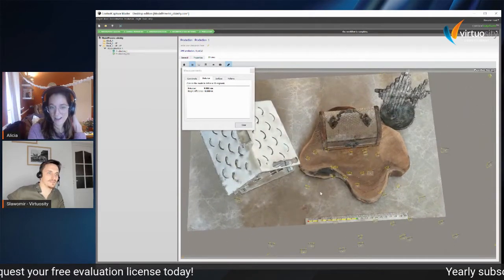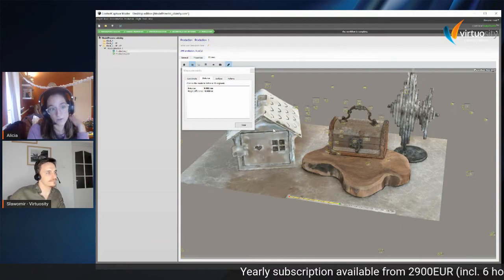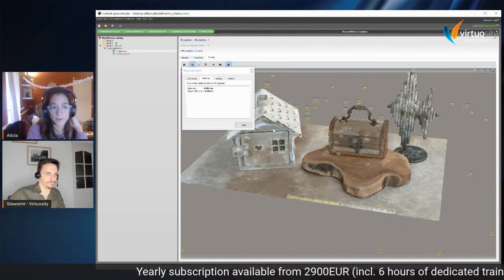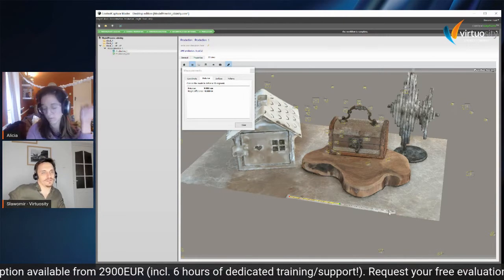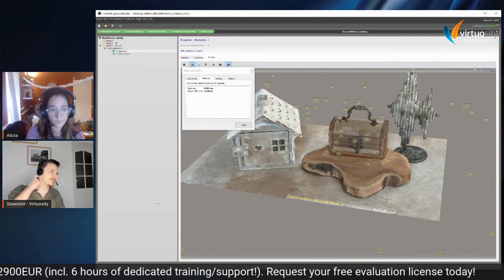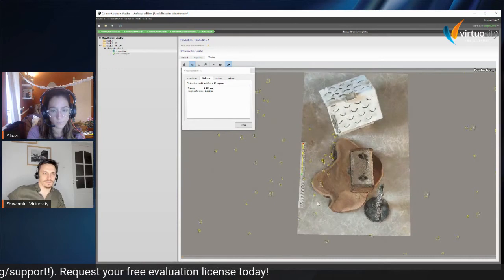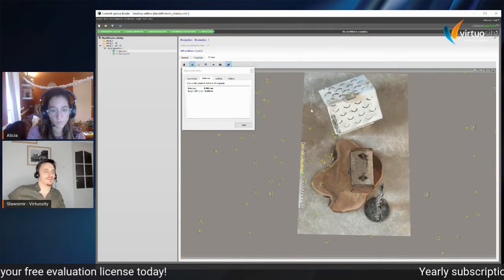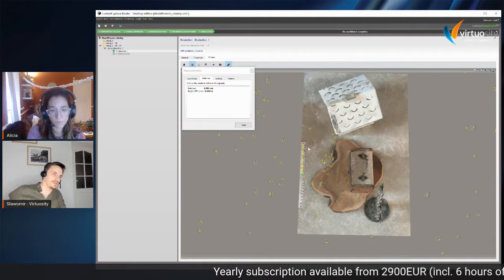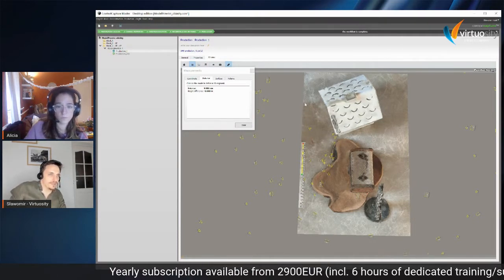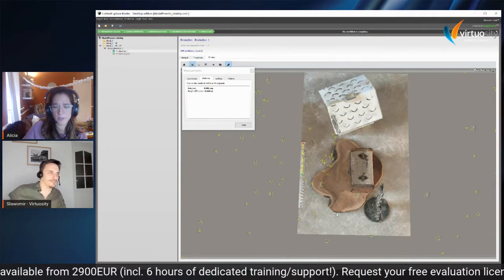Yeah, that's incredible. Did you use the scale constraints? How do you scale the project actually? Yes, in fact, I just lay down this scale bar here and create a scale constraint. If I were interested in getting also a good scale in this direction here, because right now, if we are scaling in this direction, we have to keep in mind that each scene will just scale in one direction. And I'm not speaking about the band right now.